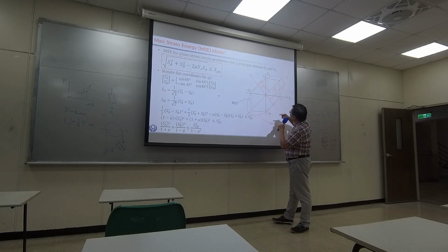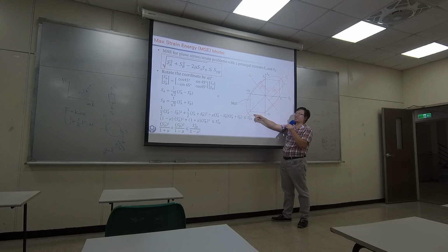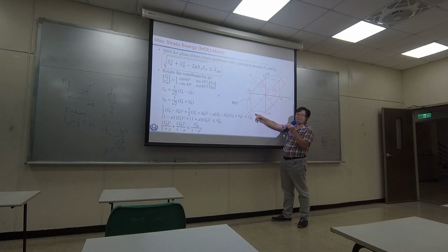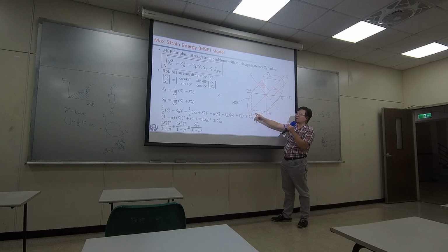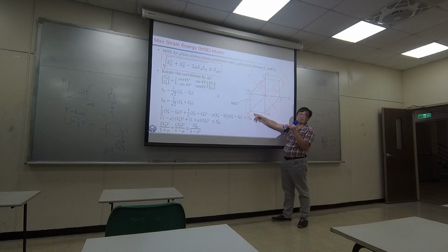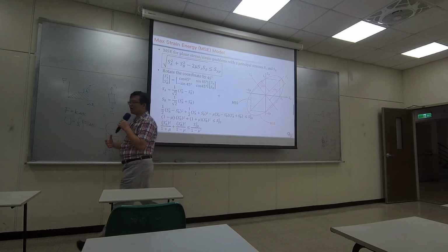Okay, you allow a loading condition, for example, right here. The maximum shear stress model doesn't allow a loading condition over here because for that model, a design under a loading condition here is violating the yielding constraint, yielding criteria. But in a different concept right here, it allows you to have a design right here. Okay, so that's the difference between the two models.